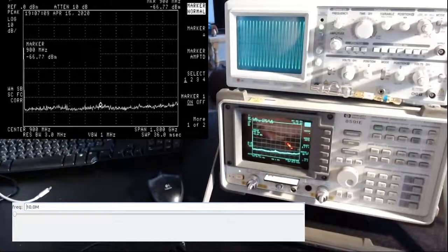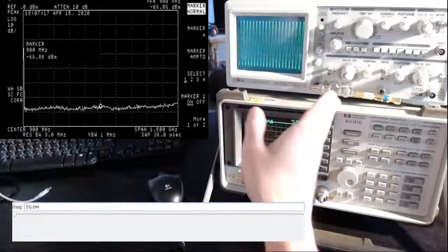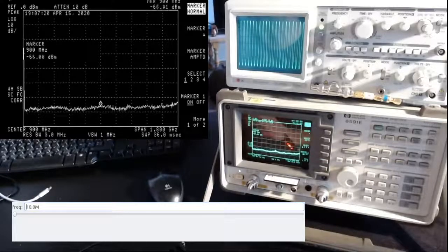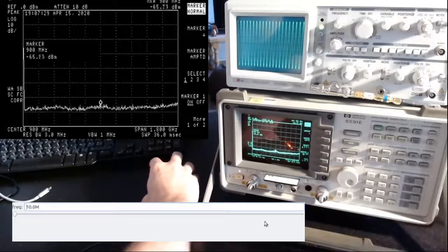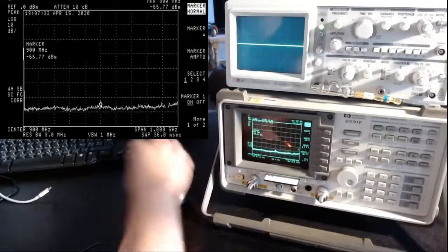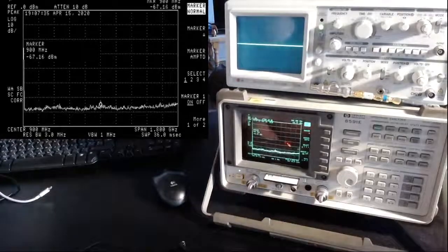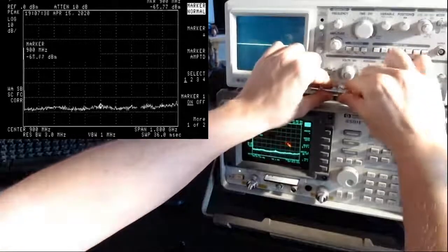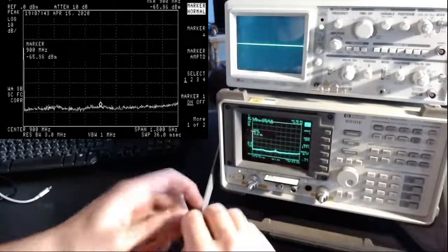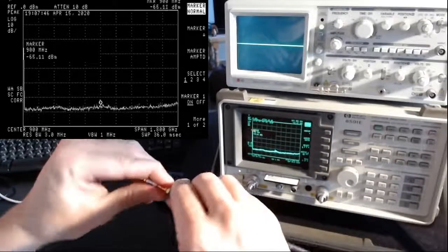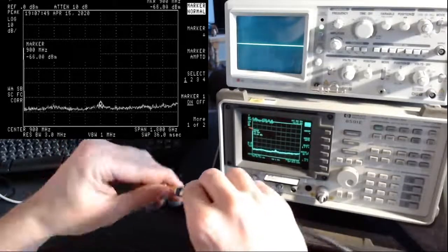Which is great, which is what we wanted. So now with this oscilloscope I basically check that indeed the signal is okay, it can be inserted in the input of the spectrum analyzer without the risk of damaging anything. So I will just do that now. So first I will stop the HackRF. So the HackRF is now not outputting anything. And then I remove this from here and connect to the spectrum analyzer. So again, I will make very sure that all the connections are properly connected here.